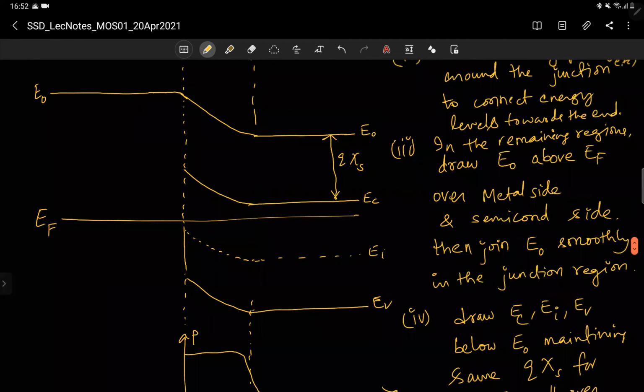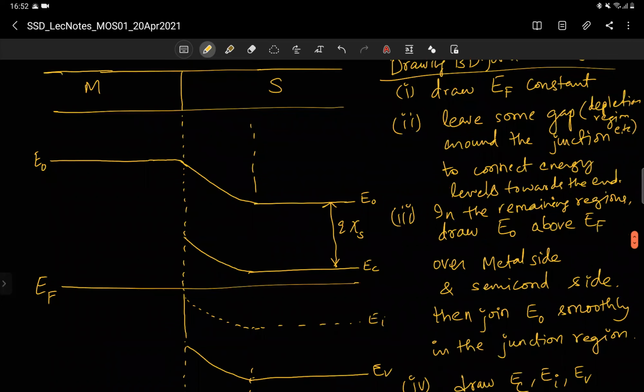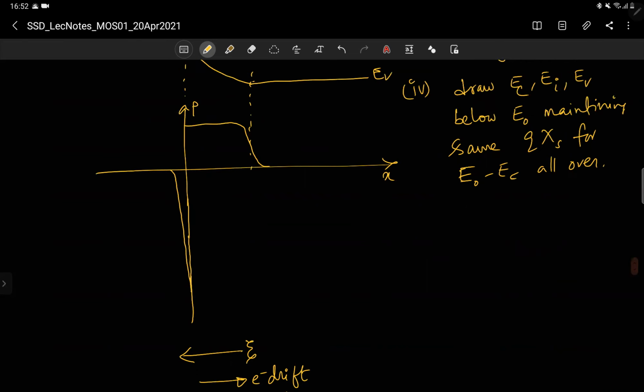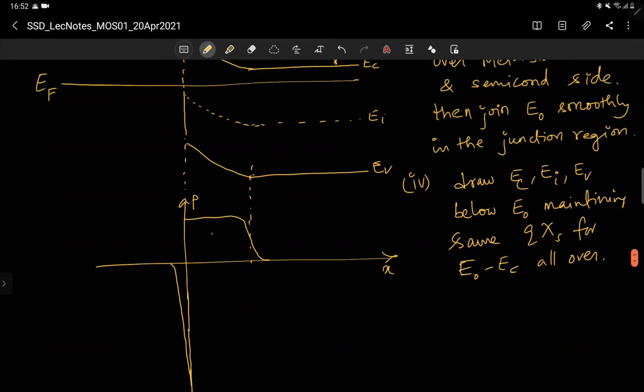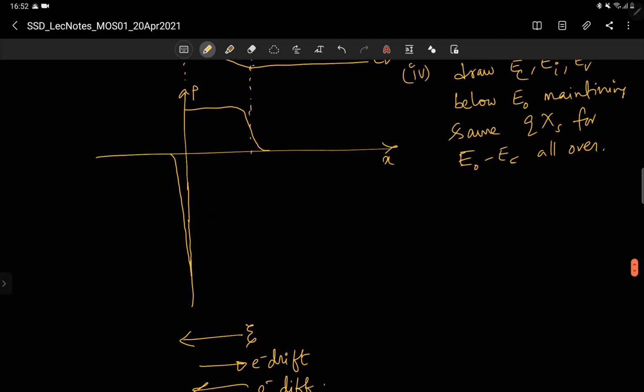Now if you see what happens when we apply positive voltage. So we have seen that this kind of metal semiconductor junction has a potential difference. So when you integrate this, from this rho, you will get the electric field in this direction. So there is a built-in potential. In what direction is the built-in potential? In this direction there is plus, because the electric field is coming from positive charge. So this is positive charge, this is negative charge.